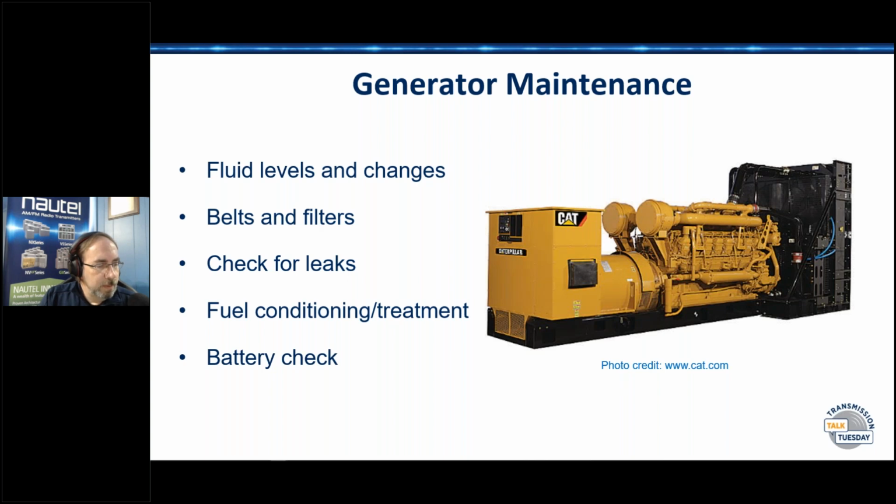Hardware cloth also for any openings in the generator. For example, on our generator up north, we have holes in the bottom of the frame where they would pick up the generator initially to move it. I put hardware cloth over those holes to keep the mice and other critters out. Also, when we were talking about batteries, I learned this just recently. I use LEA surge protection at a few of my sites, and I found out the units have button cell batteries in them, so you want to look at those too. If your display's gone on that surge protector, take a look inside. There's probably a button cell battery in there.